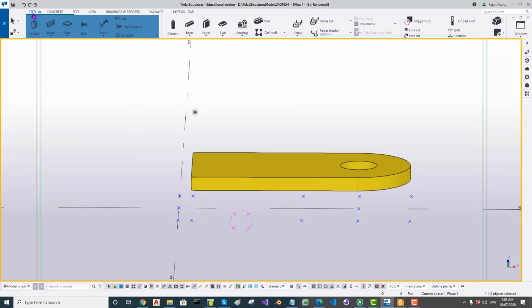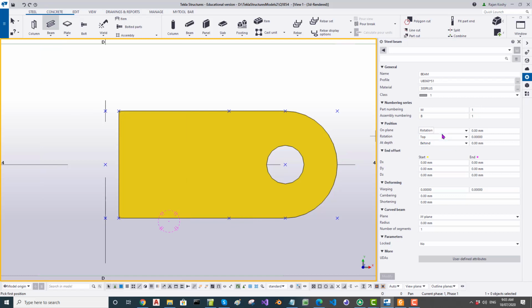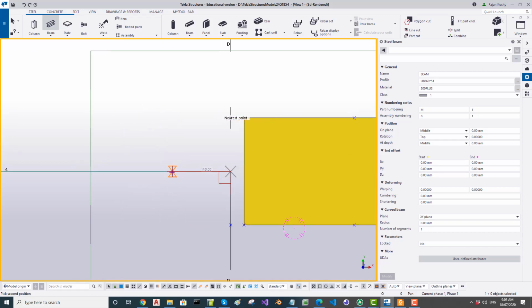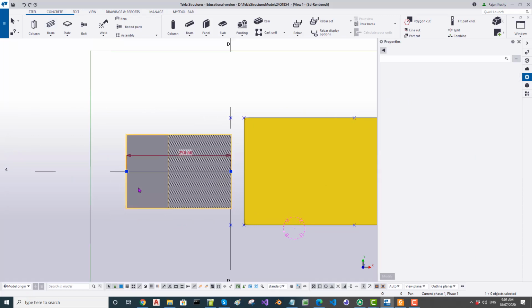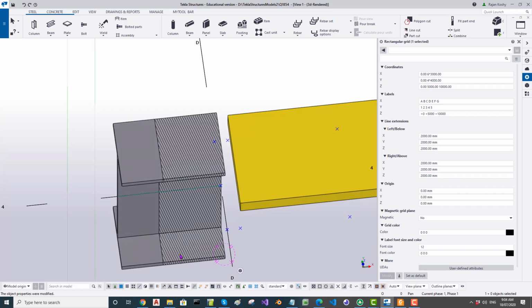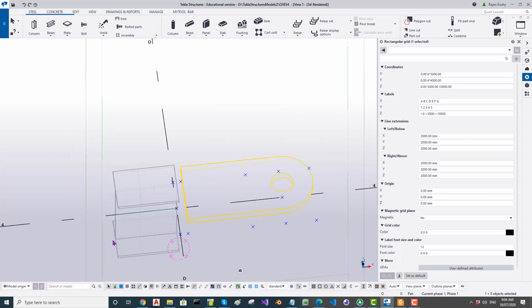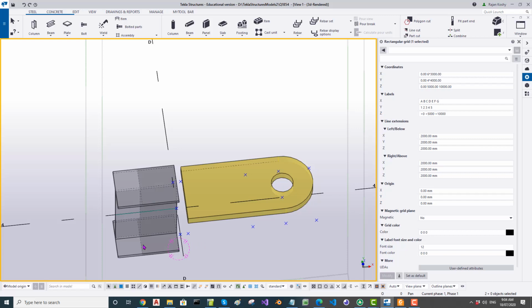Okay, so I go to steel, I go to beam, go P, I press shift beam. I will set the plane in the middle. At depth I will also keep in the middle, and then I'm going to draw a beam from here. This endpoint doesn't matter. That's my source, and another one destination. But here for the destination, I'm going to change the rotation from top, that's the top now, to below. Modify. So I have a source beam and a destination beam. Now to enable me to select properly, I'm going to change the shading by Control 1 to wireframe. So I can select that and then select this easily. Okay, or Control 2 maybe. That also may be better.